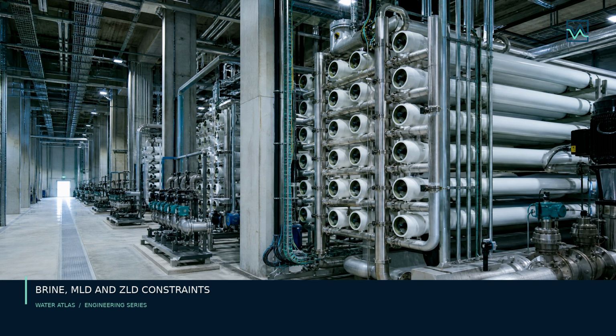Engineering practice in 2026 relies heavily on robust multi-barrier intake strategies, including subsurface beach wells and seabed galleries that drastically reduce silt density index and biological loading. Once the water enters the plant, the pre-treatment train incorporates dual media filtration, polymeric ultrafiltration, and precise chemical conditioning, including pH adjustment and anti-scalants to prevent mineral scaling.